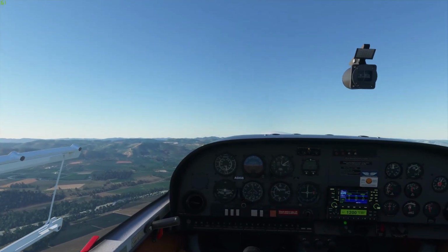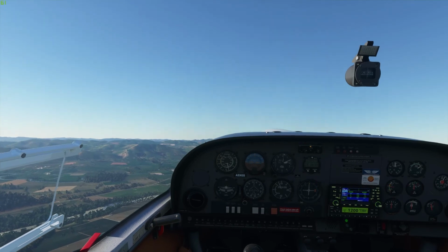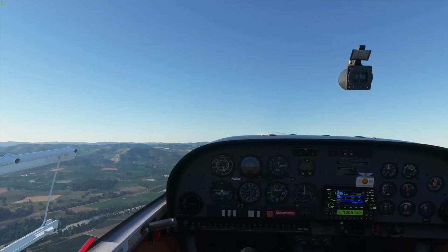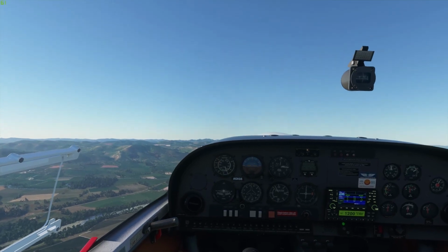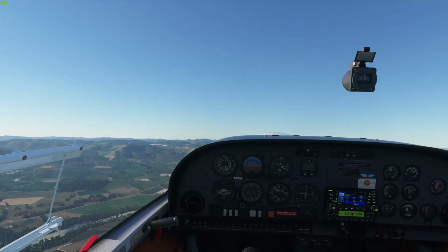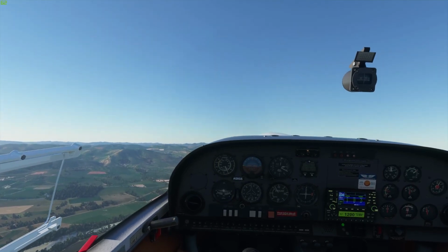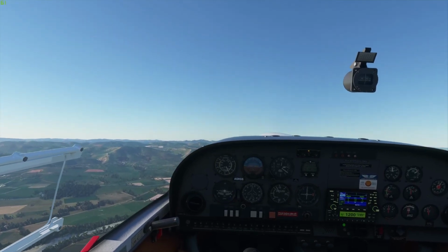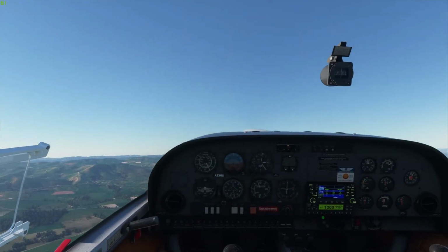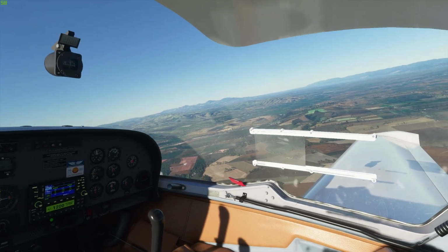And we'll get an idea, because if we hit 70 knots here, and the rate of climb decreases, we know we've got more drag than lift going on. So that's 70 knots. Haven't seen a big change in the rate of climb. It's still sitting around 600 or 700 feet a minute. Just trimming for that. Okay, clear on the left. And we'll just start a gentle right turn here.